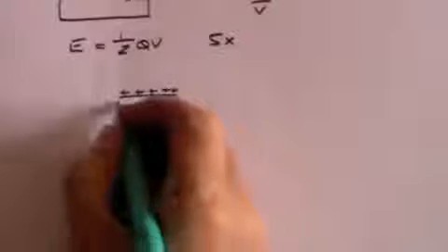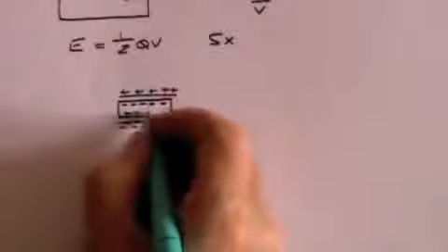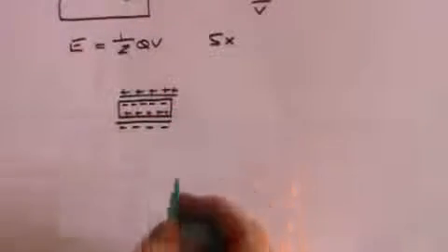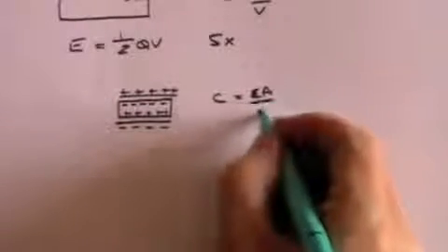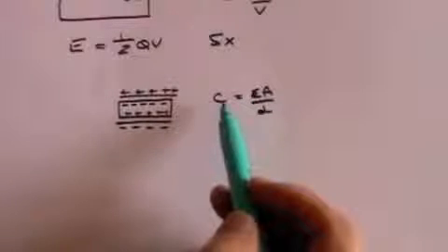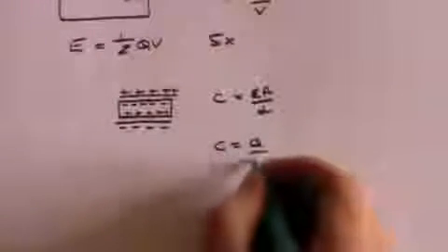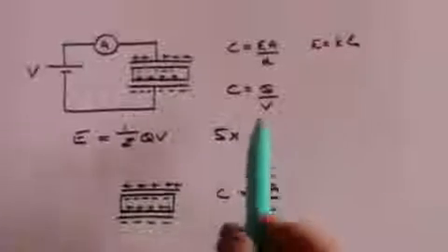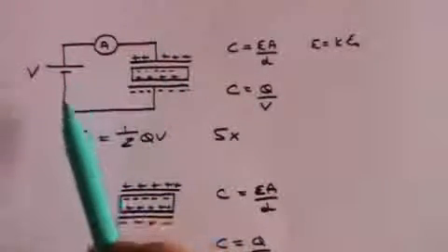Now we introduce the dielectric. We're going to use a glass dielectric again, and once again we shall get induced charges right at the edges of the dielectric. Once again, C equals epsilon A over D. And effectively the dielectric has increased 5-fold, so the capacitance has increased 5-fold. And C is Q, charge over voltage. But now the charge cannot increase 5-fold, unlike up here, where it could, because there's more charge to come from the battery.